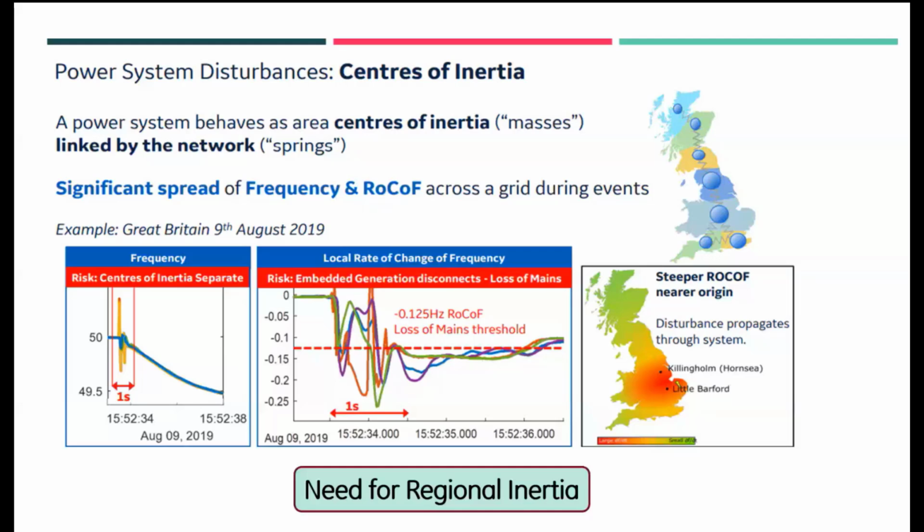So there the inertia will be less compared to the entire system, and there again the concept of regional inertia will apply. That is why the inertia distribution depends upon the architecture and design of the grid, the unit commitment philosophy, how we are going to operate the grid, the policy and regulatory requirements, and then the market requirements. Based on that, the entire picture will change.